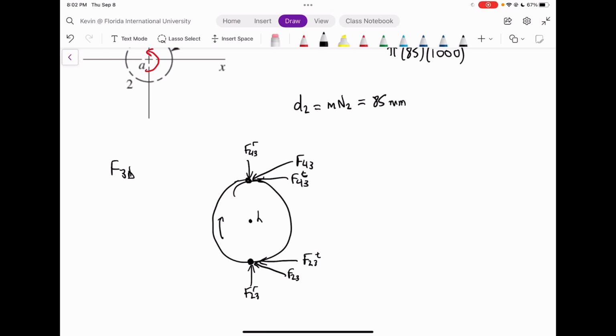And we have our shaft B in the middle, and we're going to have some sort of reaction force in the middle on the shaft to resist those forces. If we look at the two forces together, and we know that all the forces are transmitted throughout the idler, it would make sense that the force, as a first assumption, would be in the direction to the right. So FB3 would be to the right. It would be countering our F3B.